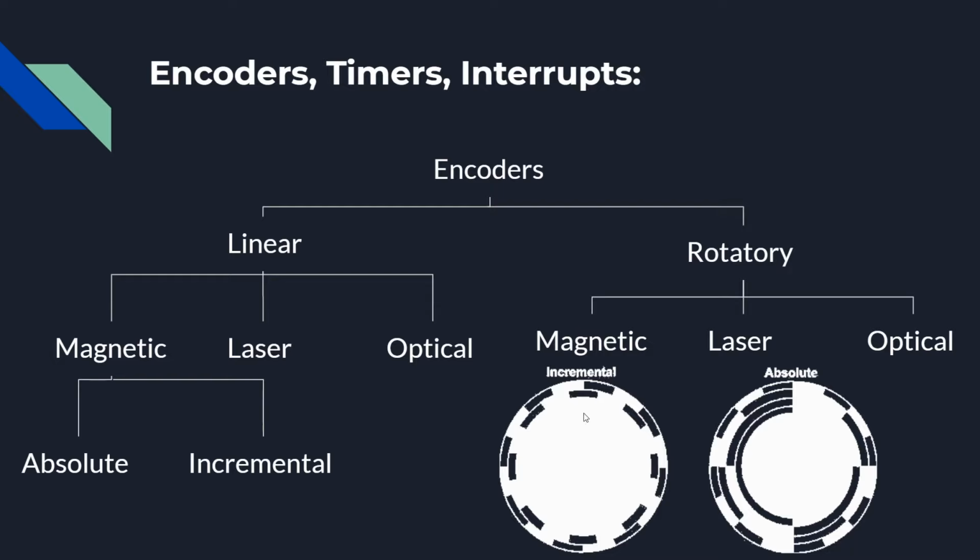And in fact, by having a disk like this, you can actually say which direction it's moving in, because we'll get into that a bit in a few seconds. We'll actually show you. But the thing is that using an incremental encoder, you can only tell the speed and maybe the direction. You don't necessarily have to be able to tell the direction, but you can only tell the speed, maybe the direction. Using an absolute encoder, you can tell both the direction and the current angular position of the motor, and the encoder would look something like this. Both of these are rotary encoders.